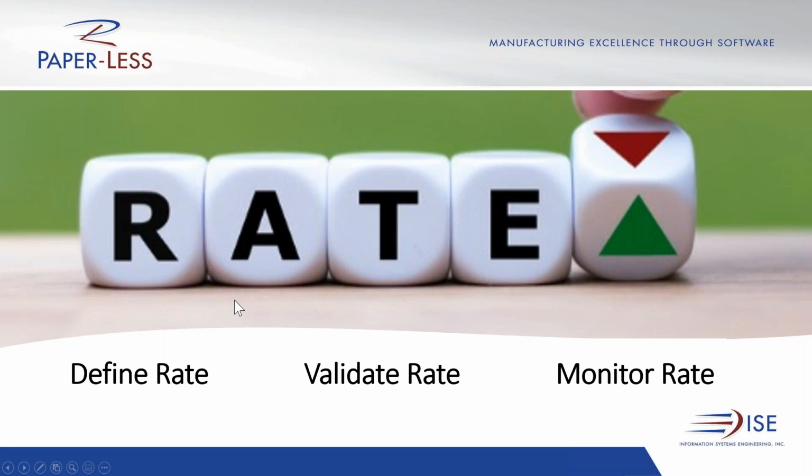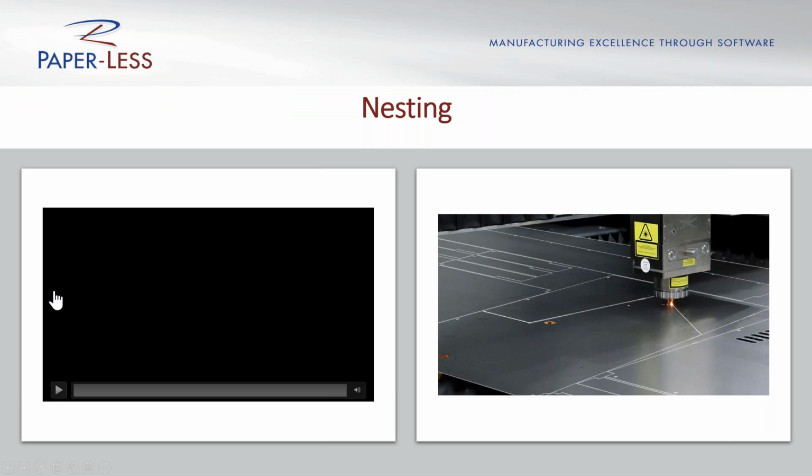So that's rates. Let's talk about nesting. It was my 3rd activity here. Nesting, a very common tool out there in the industry. It's used to optimize work, to say I'm doing things at the same time. A very common scenario is cutting sheet steel. That's what my image is displaying, is I'm going to have a piece of sheet steel. I'm going to optimize the utilization of the sheet steel to minimize my scrap, which is a great efficiency thing out there.